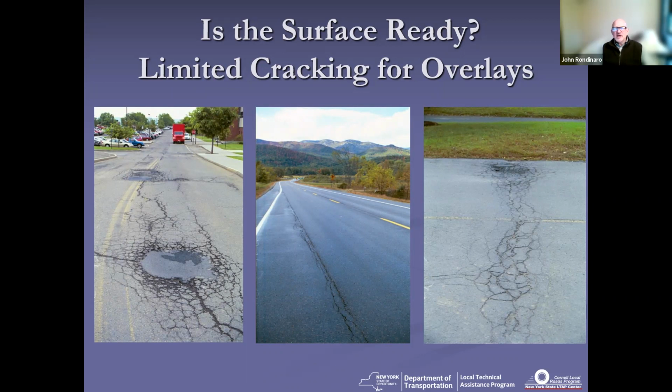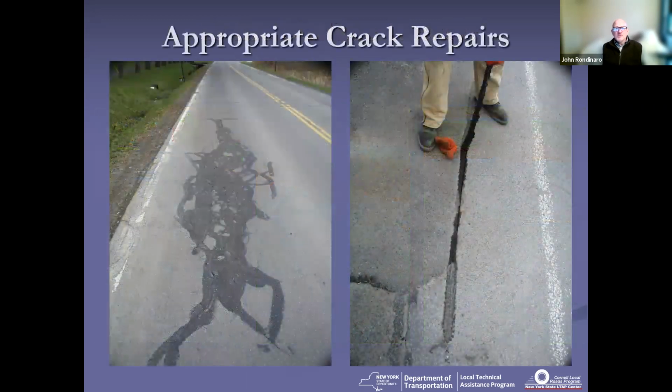In terms of the middle slide, you've got to get those cracks treated, got to get them sealed before you do your overlay, and preferably you do that the season before. And then in terms of the right-hand slide, if this is just a localized area distress, you can do an area repair or a local repair. But if it's more extensive throughout the pavement section, you're really going to be needing to look at a more extensive treatment.